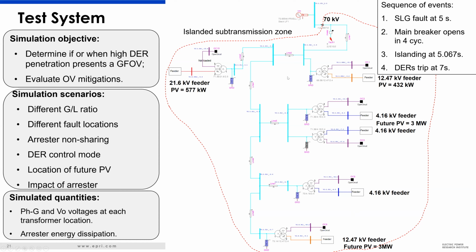So this was a sort of theoretical study. We removed the arresters and compared the overvoltage to the case where we have the arresters. Basically, in this case, arresters, if they conduct, act like a load, so they help mitigate the overvoltage essentially. But the objective was to see whether they can sufficiently modify the voltage to keep the voltage level within reasonable limits.